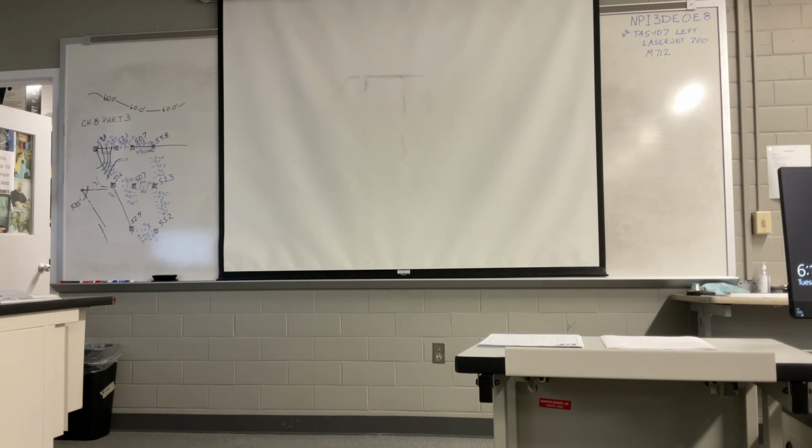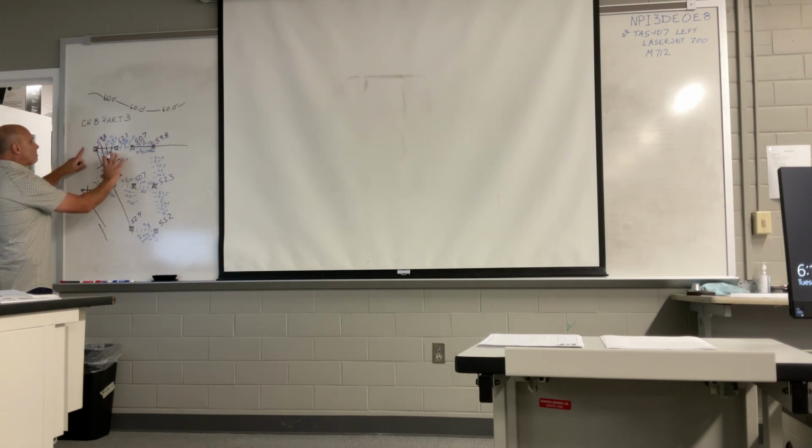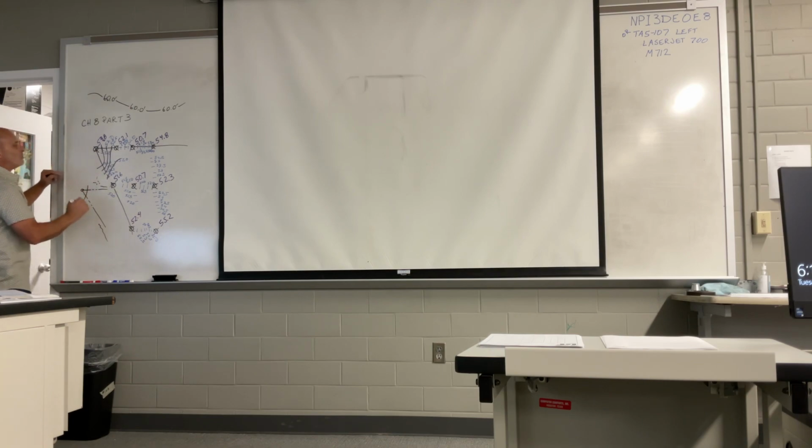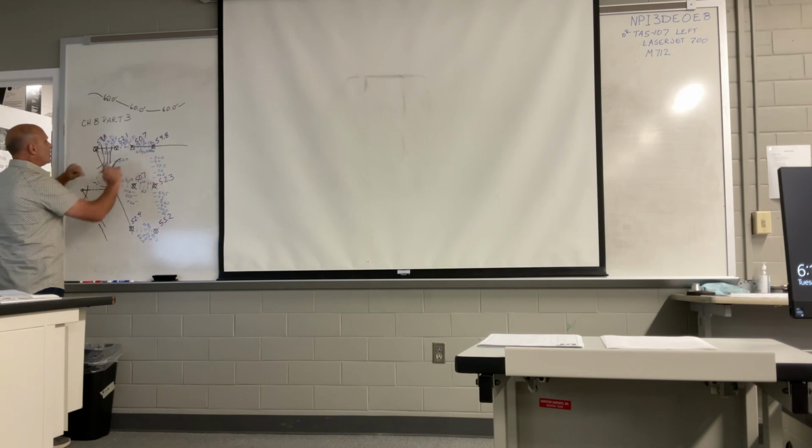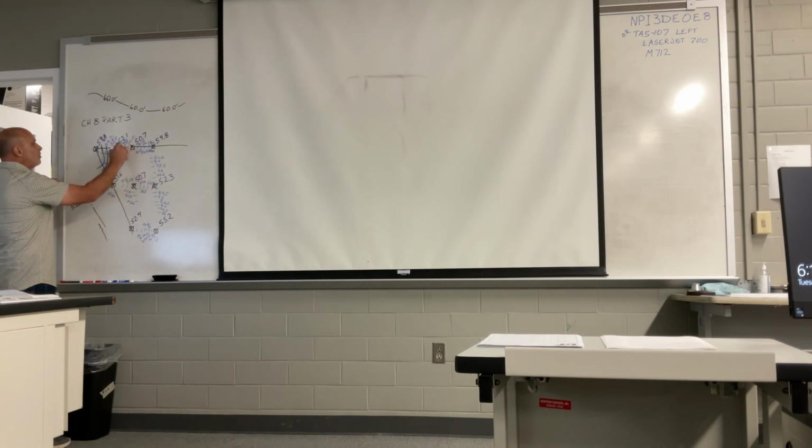Don't try to work your contour from one end of the drawing to the next. On this project, you're gonna have some contours that are gonna be going all the way or a long ways across that drawing. Some of them possibly that come down and make a dip and then go back across. Don't try to lay each contour out. Work on one area. It's gonna be a lot easier for you to work on that one area. Then when you get that one all done, now you look at this other area. See, I've got a 52.0, so that one comes in and ties in right there.